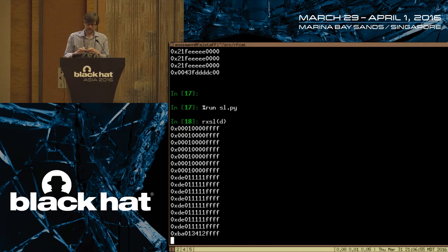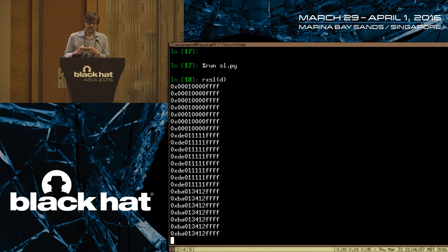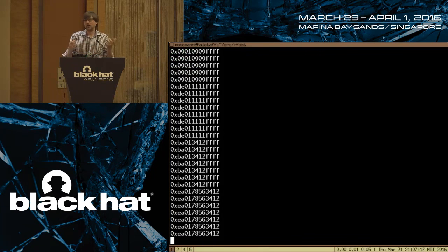1, 2, 3, 4, lock. Oh, you can see my byte order is wrong, or my nibble order is wrong, but I'm not going to even worry about that because I can just eyeball that. About 8 digits is the maximum length pin. So let me try 1, 2, 3, 4, 5, 6, 7, 8, lock. There we go. So now we can see, basically I have my order of nibbles reversed. In my head I read those as 1, 2, 3, 4, 5, 6, 7, 8, 0, 1, EA.